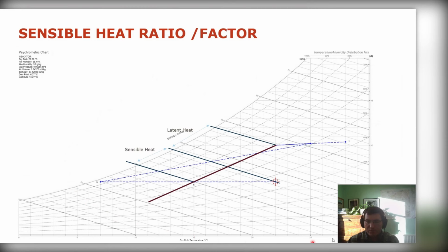That's the same graph as before, I just zoomed in on it. And what I've done is I've looked at the 2 points. 0.3 is the conditions in the room, and 0.6 are the supply conditions. And let's say we worked out that they actually match really well. They can correctly absorb the amount of sensible and latent heat. What I can do on the graph is draw a straight line through them. And I can also work out how much of my heating is latent heat, how much is sensible.